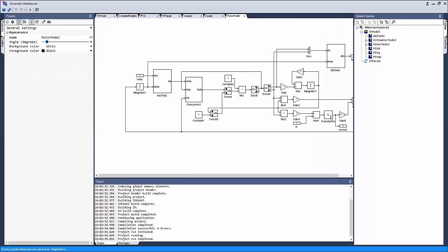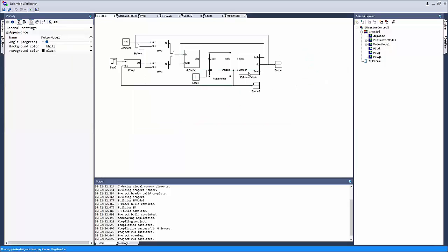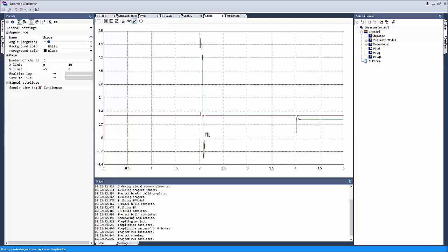So if you go to our motor model, in addition to inertia J, we also have a frictional component B as well, so 1/(Js+B). So there is going to be a residual current to sustain the frictional torque that is needed, the viscous friction due to air.